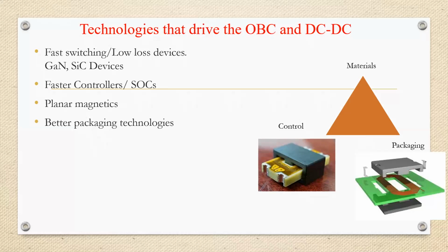What is the advantage of MOSFET and IGBT? How do the power losses compare when you use an IGBT versus a MOSFET? Both MOSFET and IGBT come under voltage controlled devices, but the BJT comes under current controlled devices, and the IGBT and MOSFET also have a bidirectional power flow nature. But which switch will you prefer to develop a DC-DC converter? If it is a simple DC-DC converter you need to implement, which switch will you prefer for your particular product? And what are the better packaging technologies you will use here?